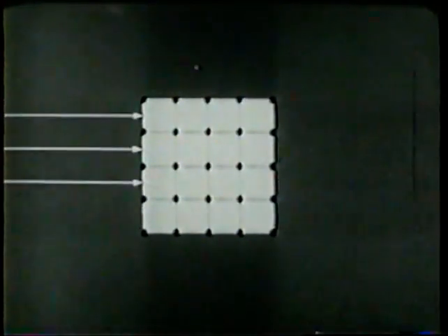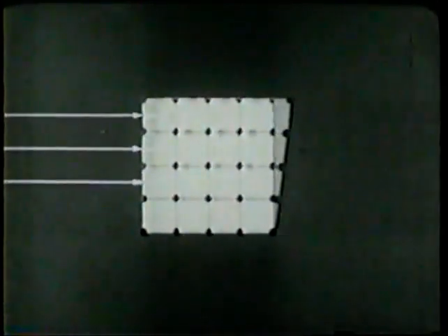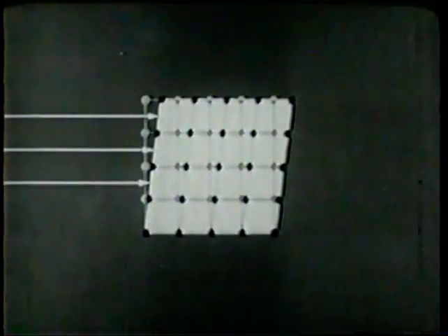Through such movement, a crystal may undergo two types of deformation. The first is called elastic deformation. When small external forces are applied to the crystal, atoms on the lattice are moved slightly from their normal positions and the lattice structure is skewed. When the forces are removed, the atoms return to their original positions and the lattice recovers its normal shape.